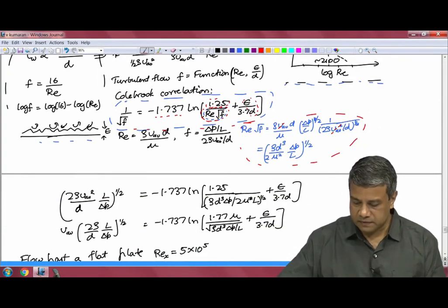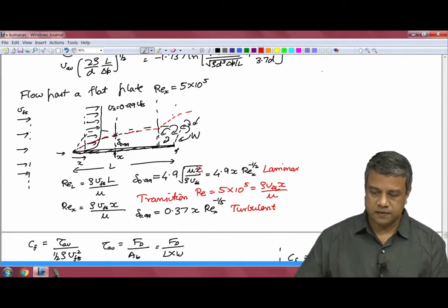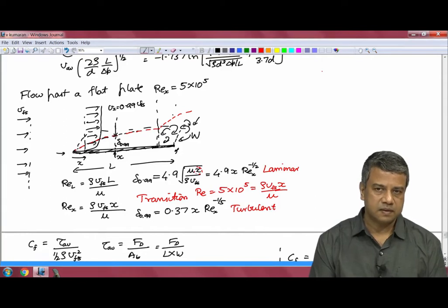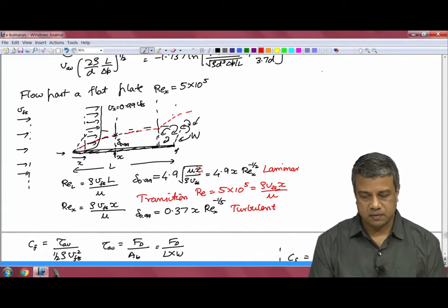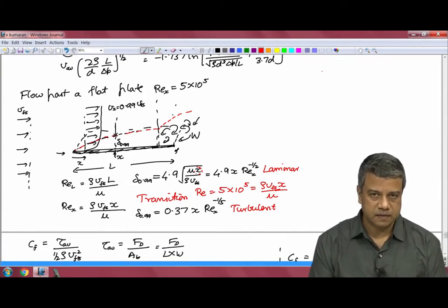We looked at the case of a flat plate as well. In this case, the flow is not fully developed, though it may be steady on average. That is because the fluid that is incident on the plate, that is tangential to the plate surface, has to satisfy the no slip boundary condition at the surface of the plate.